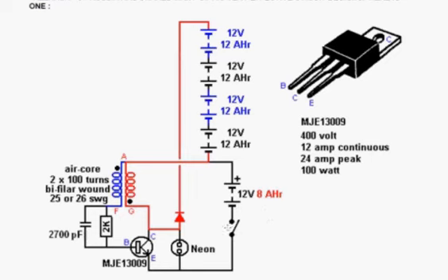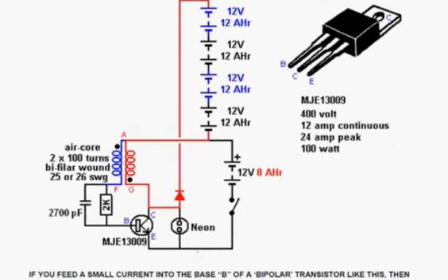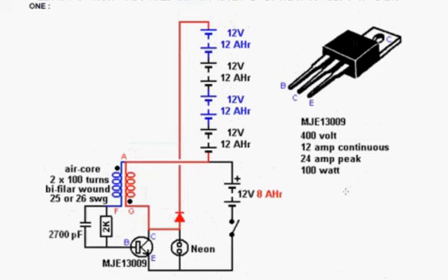You don't have to have one. You can just connect to the battery. And it has a neon, which is effectively a spark gap. This particular neon spark gap is typical. It's called a neon bulb, and it triggers somewhere between 90 volts and 110 volts. Now, the reason it's in this particular circuit is that this circuit is sometimes referred to as a Joule thief. But this is a very powerful Joule thief.